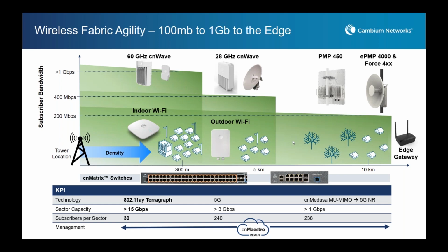If you want to get about a gigabit per second, so if you want to get MCS 12, you're talking about 600 meters. 1 gigabit, you should be able to have well over a kilometer. That's with no rain. As soon as you go in a rain region, it will drop. So if you're talking about 4 nines rain, yes, you are talking around about 200 meters. But that's still one of the longest ranges that you'll get on a 60 gig radio.